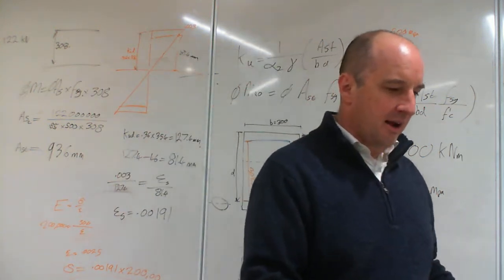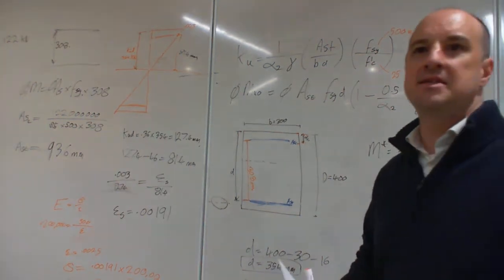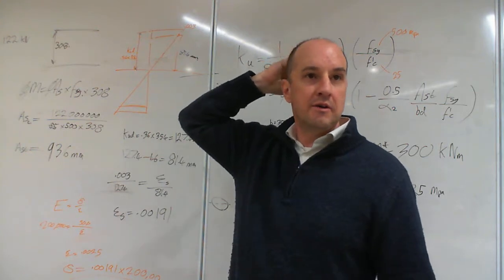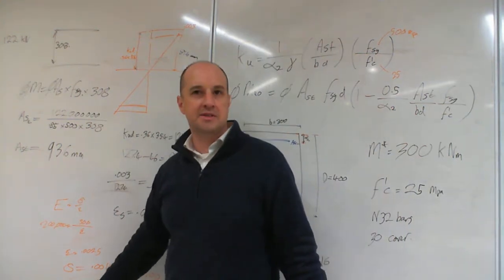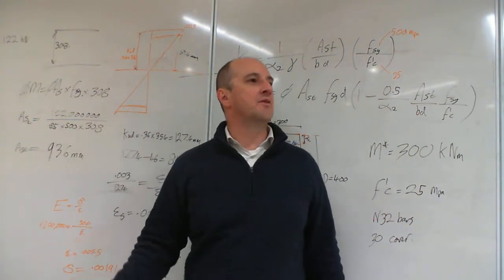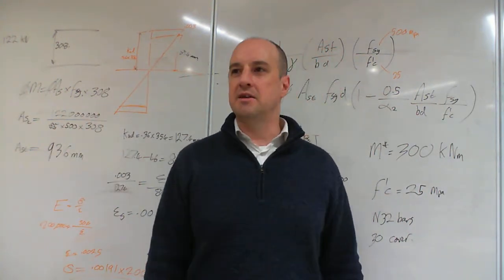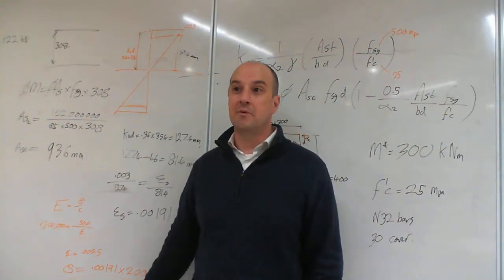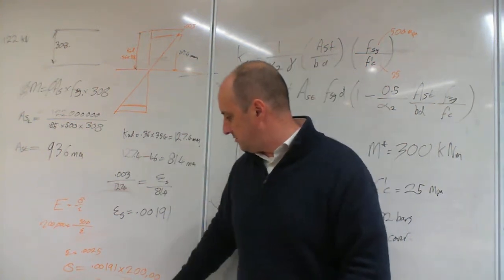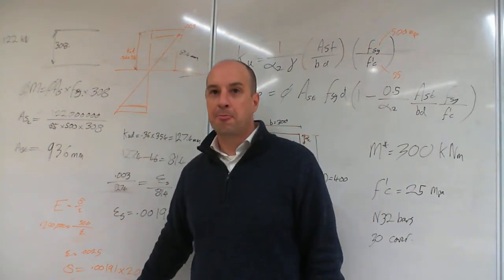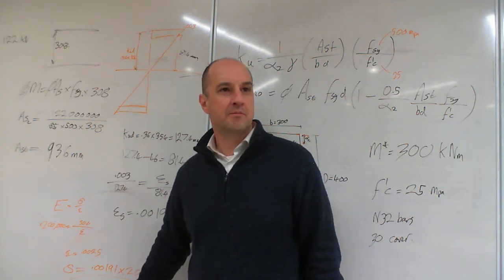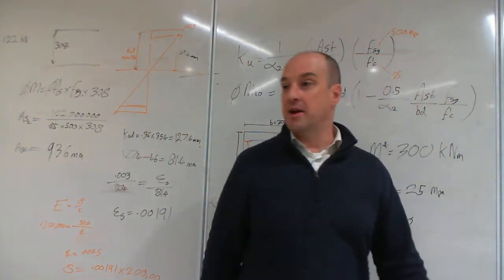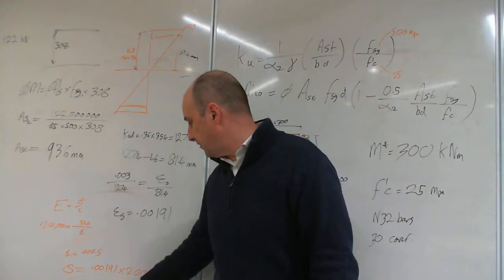All right. The last complicating factor is that steel is buried inside concrete. So if we take that full amount of stress of steel, then we have to compensate for it by giving it a little bit more concrete, which is crazy complicated, so we don't do that. What we do is we pretend that some of that steel is concrete, and we just use the remaining steel. So the concrete has got a stress of its own. Remember there was 25 MPa concrete? It's not quite 25 MPa, it's actually alpha 2 times 25 MPa is the stress in the concrete there. We take that off the 383, so let's work out that.